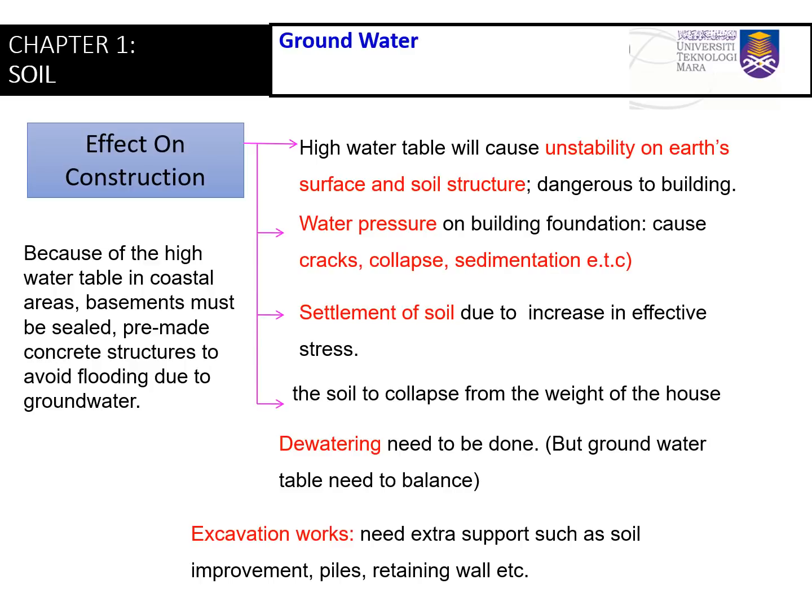So if you do construction in basement, we will learn more about dewatering. So you need to take out the water. And excavation work need extra support because the water is high. The soil is high in moisture. So you need to have support.